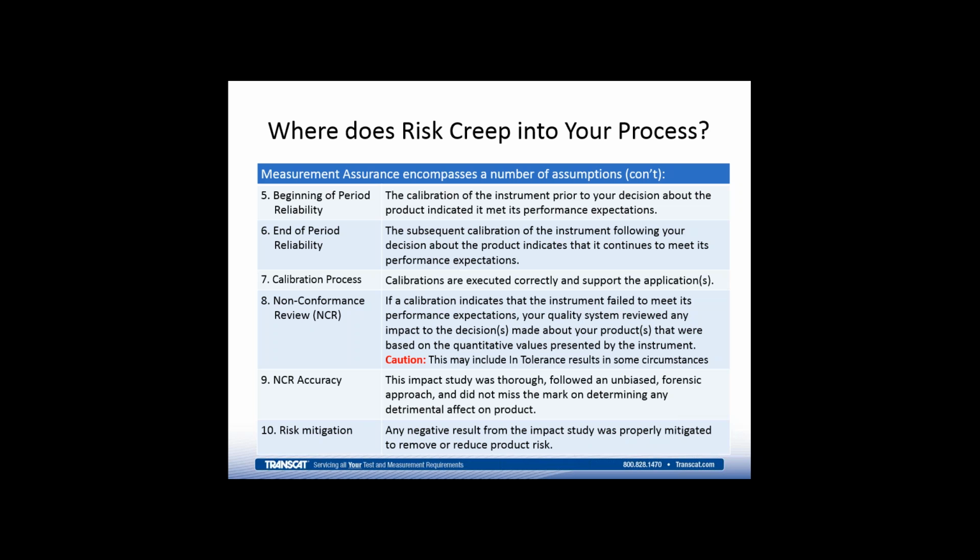And then once you get the data back from the calibration, typically, like I said, if it's out of tolerance, you're going to do a non-conformance review to see if there was an impact from the calibration data to the product decisions. And again, that can also be impacted for in-tolerance results if you have low ratios.